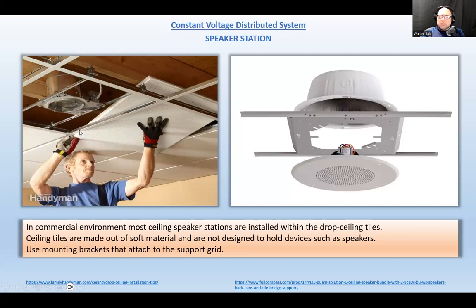So the weight of the speaker is mounted onto the railing, and you just cut the hole through the ceiling tile and mount that speaker. So this would be on the top side of the ceiling tile here, and this baffle would be screwed into that railing from the bottom, so you could see a nice speaker baffle on that, right?